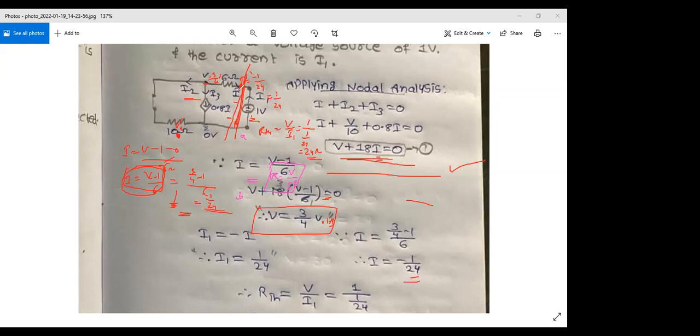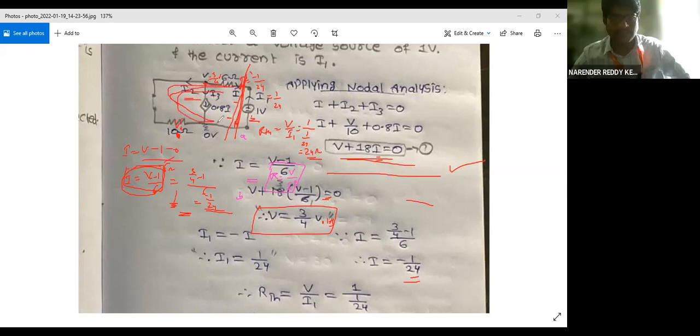So it will be greater than 10 plus 6 here, right? See, sometimes you may even get less than 16 as well. Why? Now these two are connected in series, so I can get that the resultant is more than 16, right? But in some cases, you can get the value of RTH for some dependent sources less than 16 as well. So that doesn't matter now.